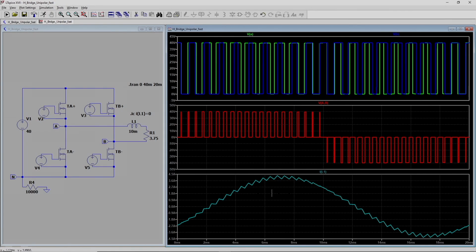What you see in this load current waveform is that it also has a ripple, and of course, we saw the bipolar PWM current waveform also; the ripple here is lesser than that. With this simulation also you can play around, change different values, rerun the simulation and see how the waveforms change.